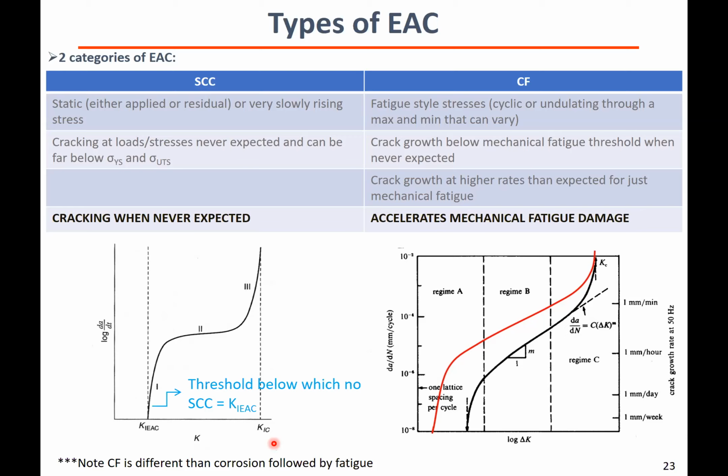and then we can predict if the material is going to fail or not. Now, if there's added issues like environmental assisted cracking, then whatever calculations you did, that failure can happen way more rapidly and sooner than you would anticipate. Okay. If you just looked at the pristine fracture toughness.